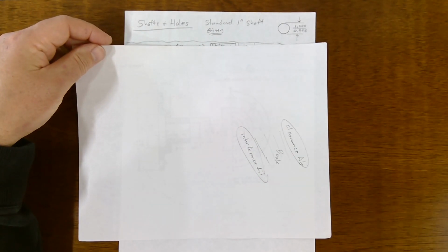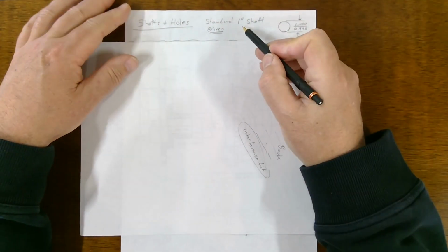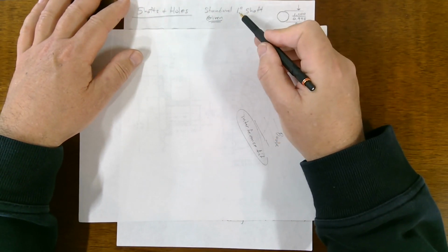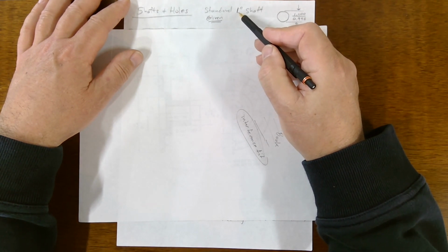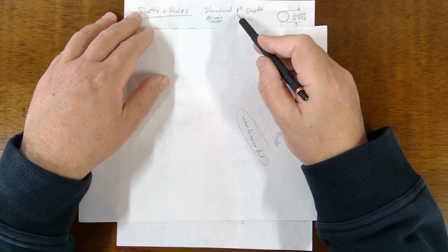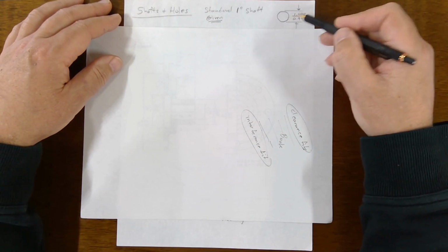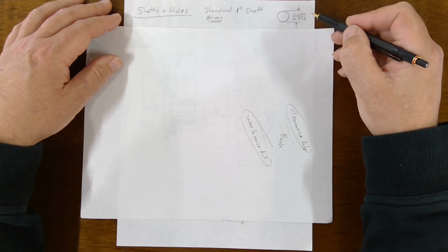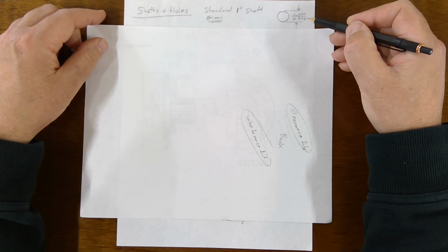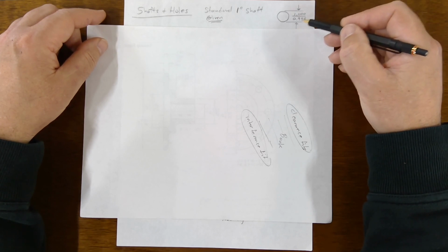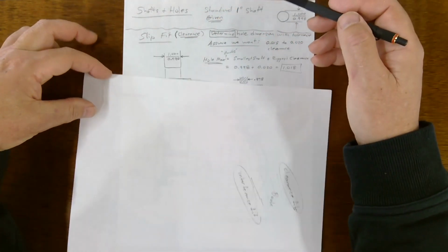So the first thing here is a clearance fit. Let's say we have a shaft. Let's say this is a 1-inch shaft, for which we sometimes use the term nominal, because nobody wants to go around saying these numbers all the time. So we just call it a 1-inch shaft. That would be the nominal size. Given a 1-inch standard shaft, these are tolerances on a certain kind of shaft used in industry. These are shafts that poke out of motors and connect pieces of rotating machinery. So let's say it has these dimensions: a maximum of 1.000, minimum of 0.998, so a tolerance of 0.002, the difference between these two. Now, let's say we want to slide this shaft into a hole like this.